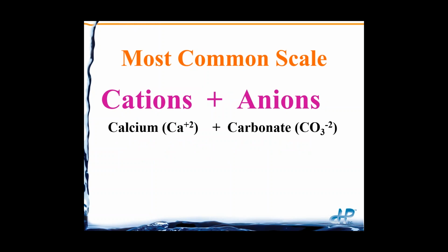If we concentrate them more than that, then we're going to scale unless we have done something in pretreatment to keep us from scaling. So again, softening or acid injection or scale inhibitor injection. The most common scale on the planet is calcium carbonate, and that's true whether we're talking brackish water, fresh water, seawater, whether we're talking surface water or well water.